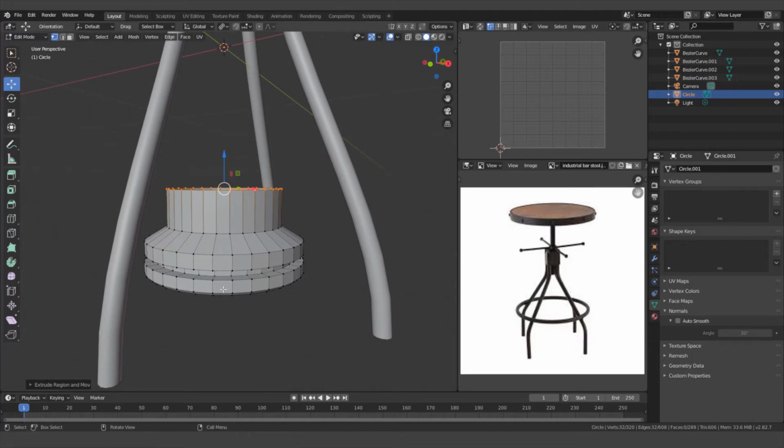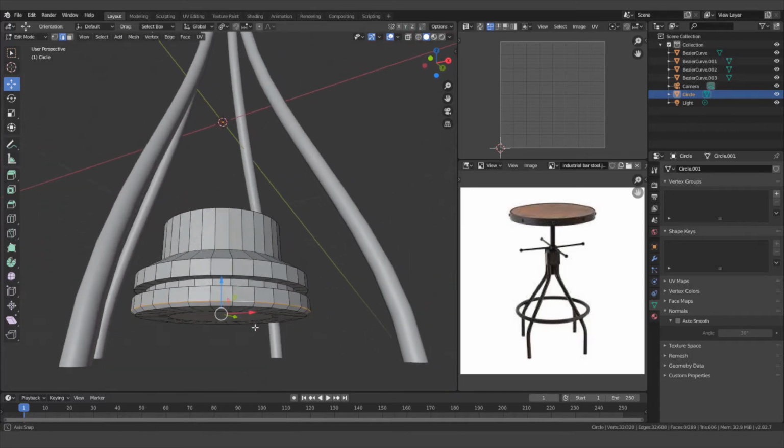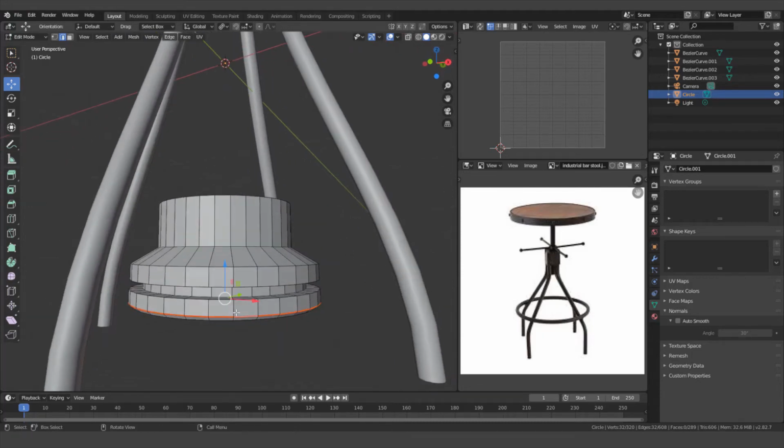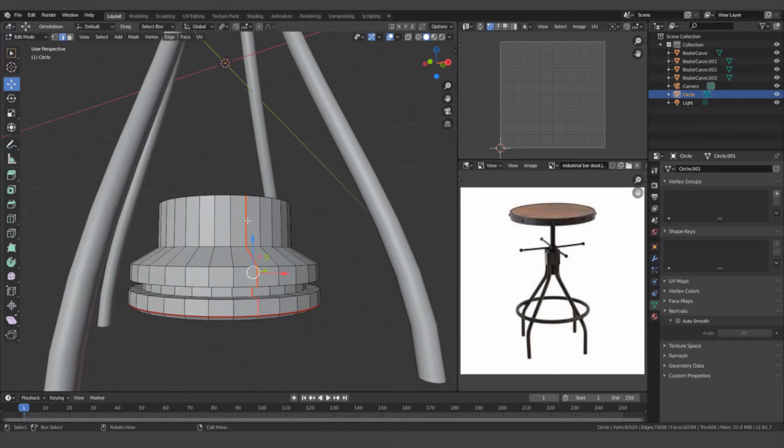Okay, cool. So I'm going to go into edge select mode because we need to unwrap this now. Come up to the top, edge select here while in edit. And let's select this edge right here by hitting Alt left click. And we can select that entire section, that entire edge loop, right click, mark seam. Okay, now we need a cross section going down this way. I'm going to select this edge here, and then I'm going to follow it all the way down until I get to this red line, and then I'm going to hit Control left click so that I've selected the entire thing. Once I have that collected, I'm going to right click and mark seam. Okay, so that's ready to unwrap.